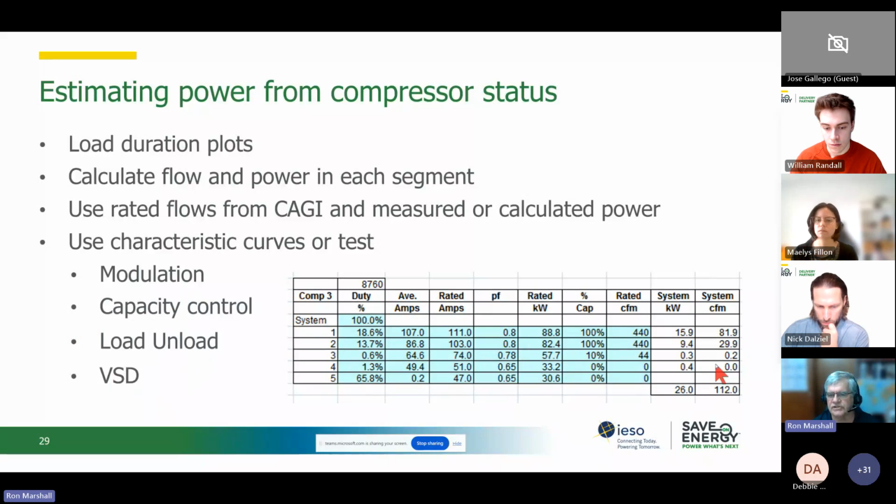And this is just a calculation from a spreadsheet that you could even make yourself, right? Where I broke down all those curves in the previous site, and the first two sections are just calculating the flow output for the fully loaded portion. There's a portion between loaded and unloaded where the compressor is transitioning between the two, and then unloaded, right?